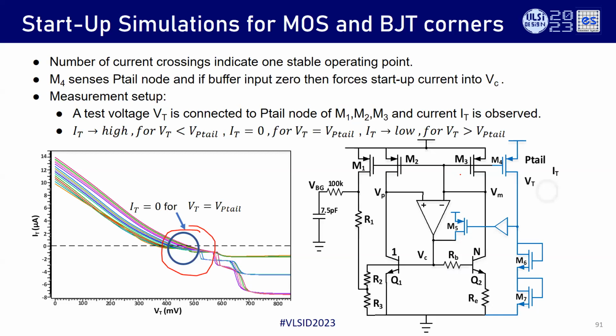So how the startup has been verified, which Rakesh explained briefly in the previous introduction. Again, we add an op amp battery here, at the op amp output, and then sweep this voltage. What you can see is this curve. The interesting thing is it should cross the zero crossing point only at one point. That says there is only one operating point. But another interesting thing is this point. When the PTAT voltage is very high, sorry, when this output is very high, the op amp will steer to one side.